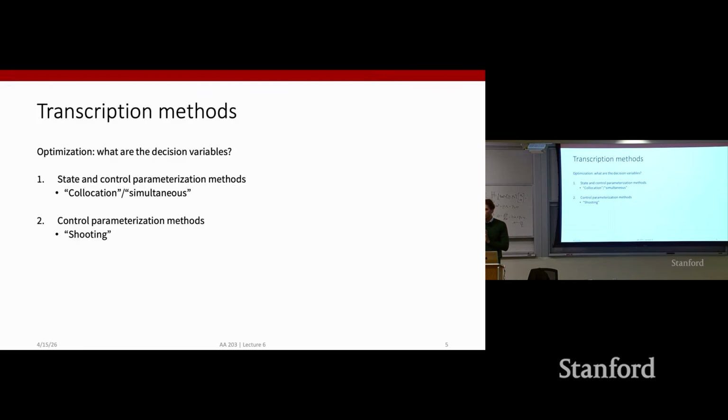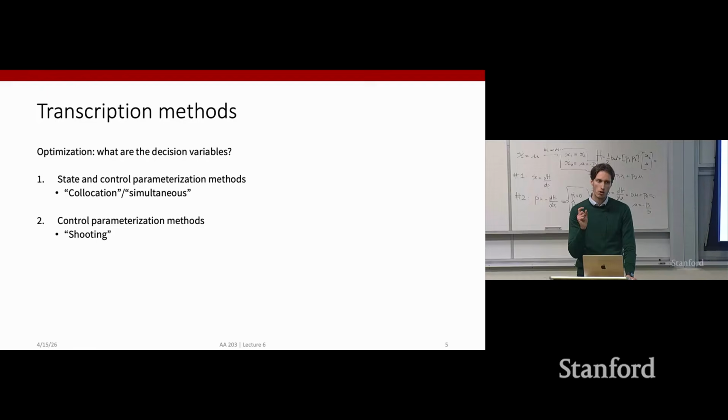we take the optimal control problem in continuous time, and we will be discretizing time and assume that only the controls are variables prone to optimization. So from the perspective of the optimizer and the solver, only the control variables will be variables we are optimizing over. The states are computed recursively through the unrolling of the dynamics.